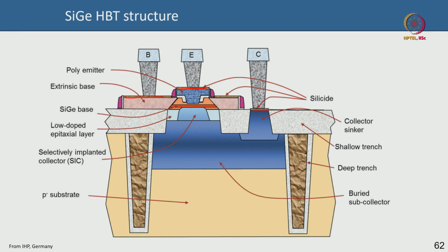Okay, right. So this is your polysilicon emitter. Of course it says polysilicon emitter. You can see this blue one here. The red one is actually the base here. You can see that this is a silicon germanium base, and this is your extrinsic, this light reddish pinkish block that you are seeing is actually your P plus polysilicon, which is making a contact to the sidewall, to the side of the p-type base. Okay, and this white one is basically your spacer, you can say, and then of course this orange one could also be spacer. There could be silicon nitride spacer, there could be oxide spacer.